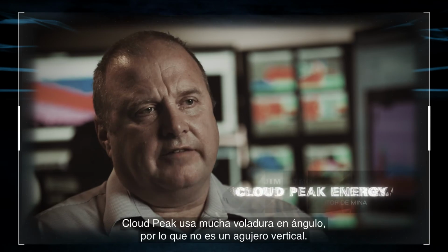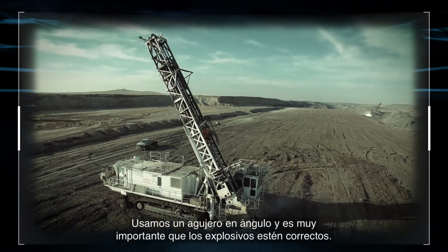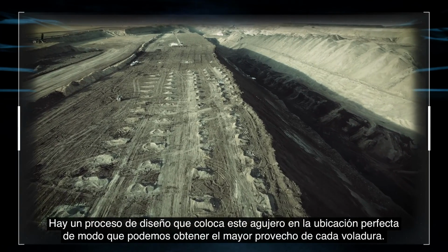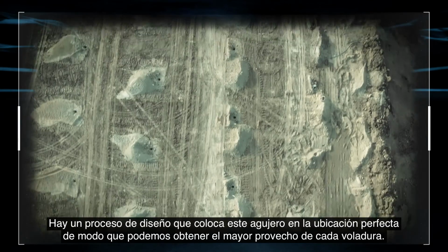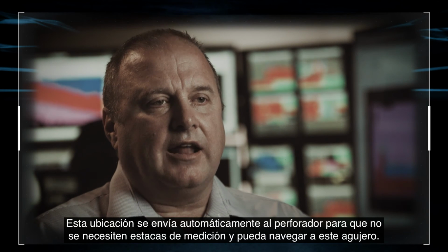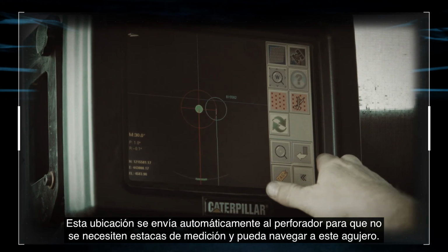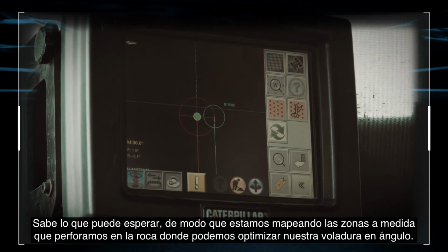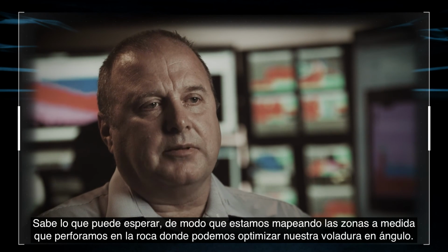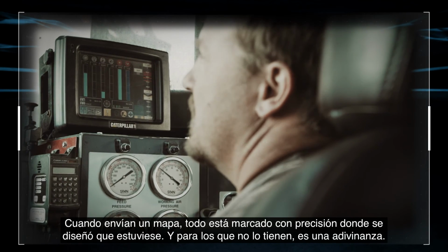Cloud Peak uses a lot of cast blasting, so it's not a vertical hole. We use an angled hole. It's very important that those be correct. There's a design process that places that hole in the perfect location so that we can get the most out of that blast. That location is automatically sent out to the driller so that he doesn't need any survey stakes. He can navigate to that hole. He knows what to expect, so we're mapping the zones as we drill through those where we can optimize our cast blast.